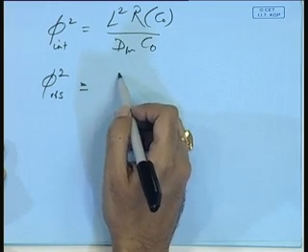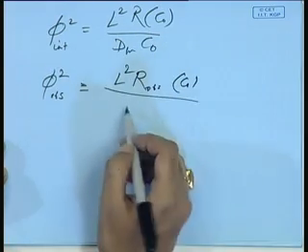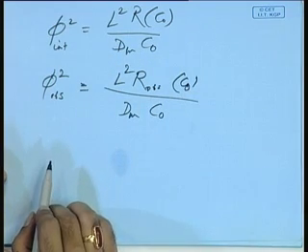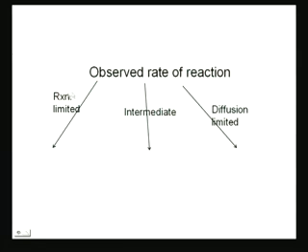The rate we are considering is the actual reaction. Right, good. So, the observed Thiele modulus is exactly the same thing, except that the rate here has to be the observed reaction rate, just as I told you. The observed reaction rate is different from the intrinsic reaction rate, and therefore the observed Thiele modulus is typically less than the intrinsic one. So, in the reaction limited regime, is the observed reaction rate the same, different, or larger than the intrinsic reaction rate?